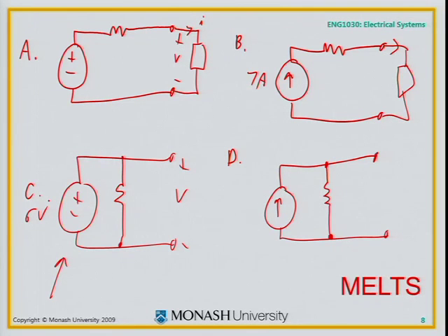Same as B. Resistor may as well not be there. Just like a current source alone or a voltage source alone, that gives us the offset but doesn't give us the slope. The two that work are A and D. A parallel combination of a resistor and a current source, or a series combination of a voltage source and a resistor.